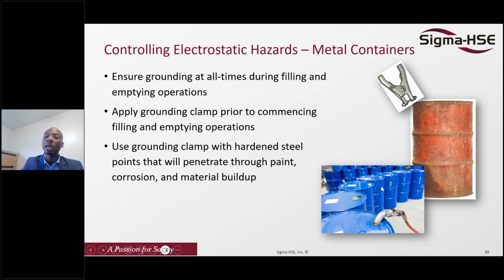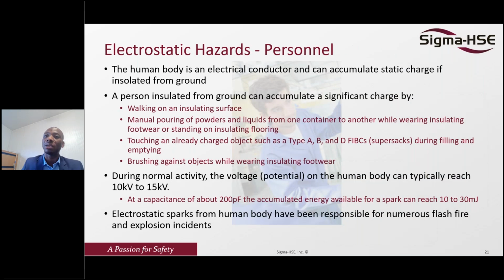Anytime you are handling any kind of flammable solvent, you need to ensure that they are properly grounded. And sometimes we might assume connecting to the clamp automatically is ground enough. Sometimes you need to ensure the metal to metal contact is complete. And actually, you can also use a megohmmeter to check the resistance, whether the material is actually bonded or grounded.